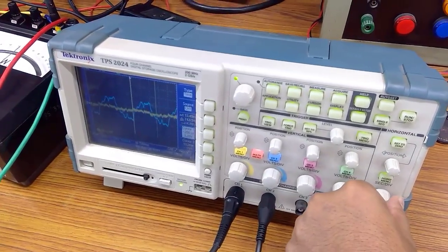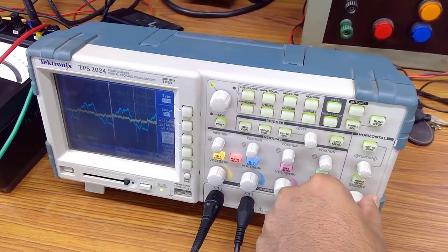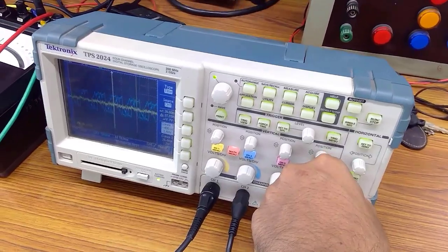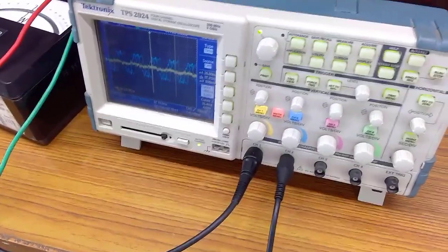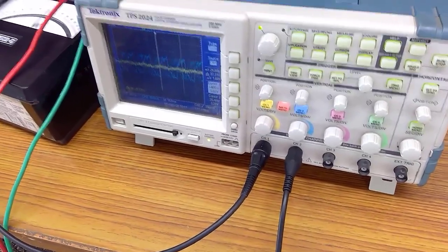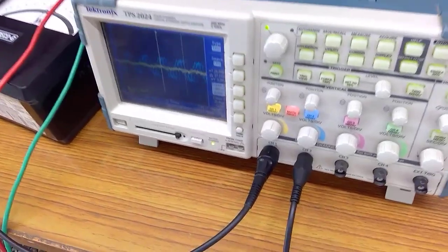Okay, but you see there is a current component now. And if you again see the harmonics there, you will see the frequency of it would be around the same as the third harmonic component. This magnitude is not 0 now. Because you are observing the sum of the currents, right? IA plus IB plus IC, and they have the harmonic component as well, and this is not 0 here.